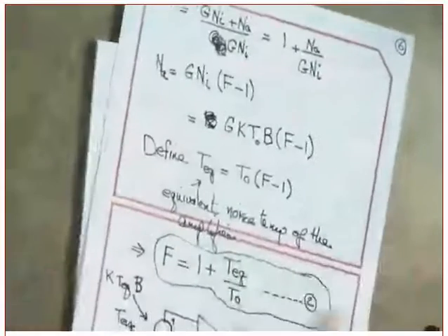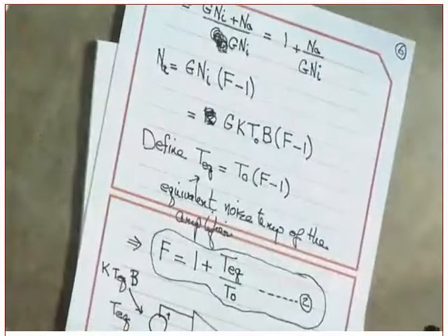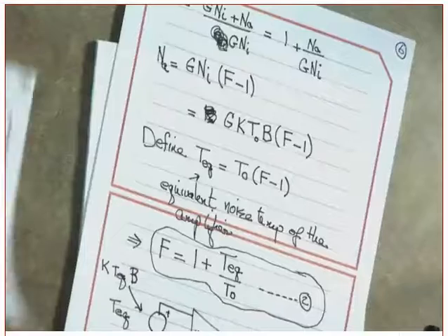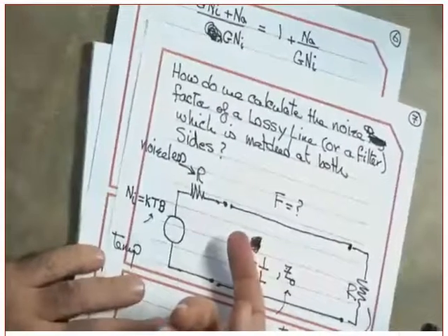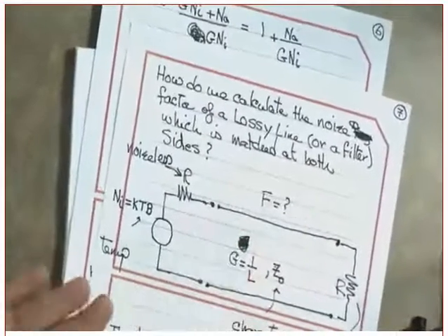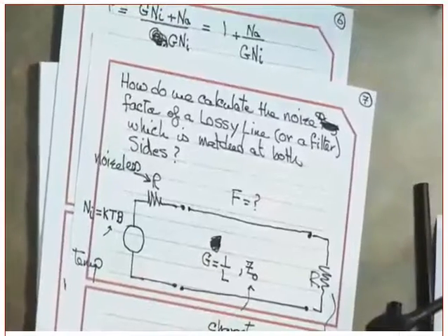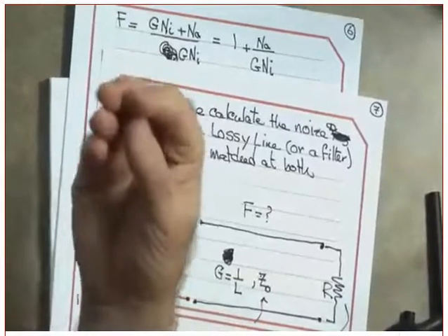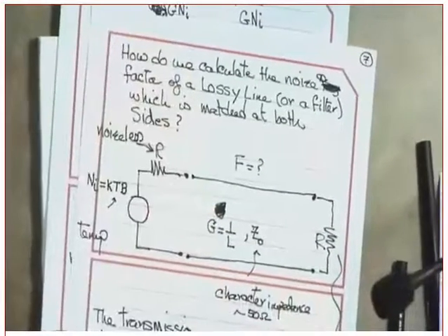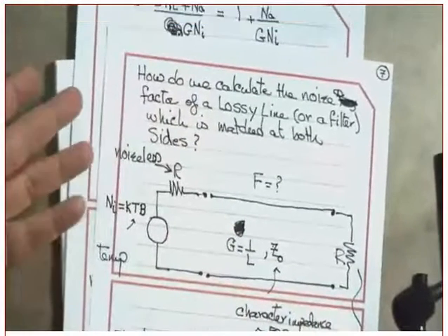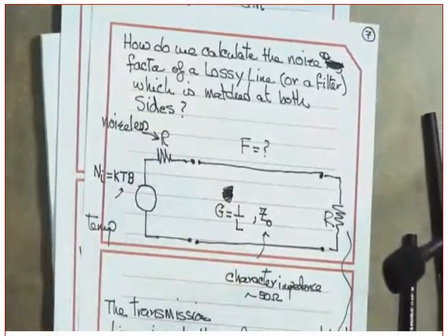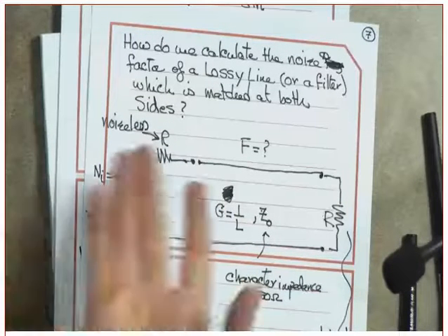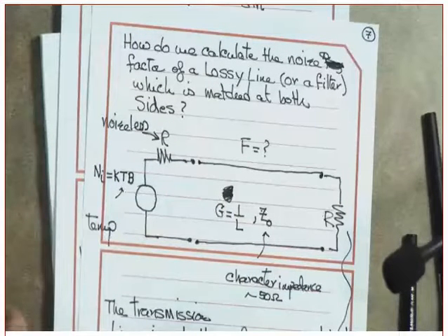By the way, let me ask a question. If this is not at room temperature, sorry, this is the source. Could the transmission line be indoors? Could the antenna be outdoors, but then the cable to the indoor? Which means the temperatures have nothing to do with each other. This T equivalent is just a make-believe temperature. It's not a real temperature.